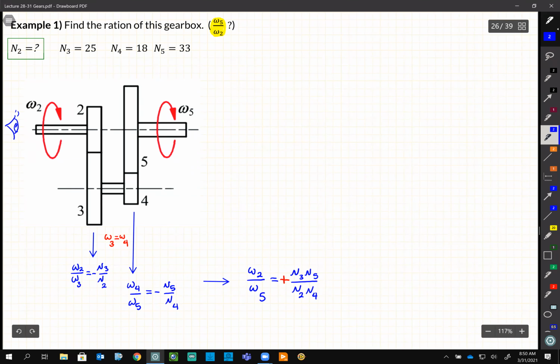You are standing in the same place, and let's say magically you can see through this gearbox. So you will see the shaft is also counterclockwise. But if you come here and stand here, this is your eyes again, then you will see it is clockwise. So remember, when we say the direction from input to output, always we are staying in the same place. We're not changing our direction. All right, so that's the first thing to keep in mind.